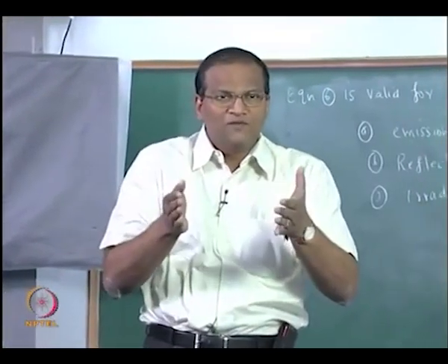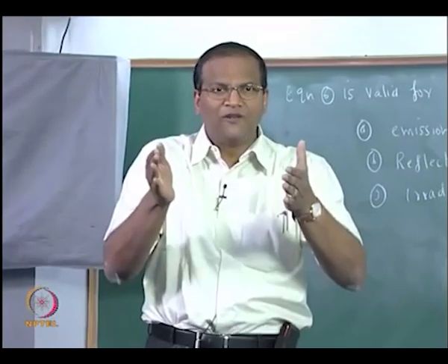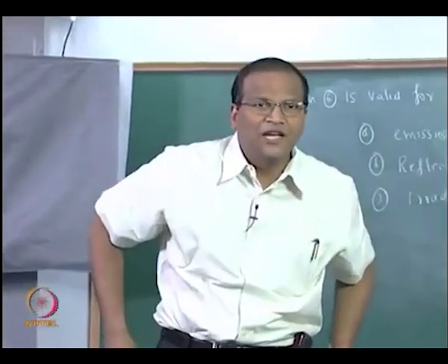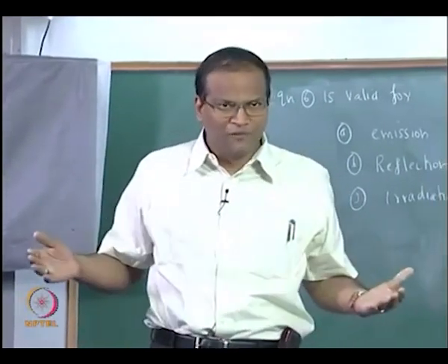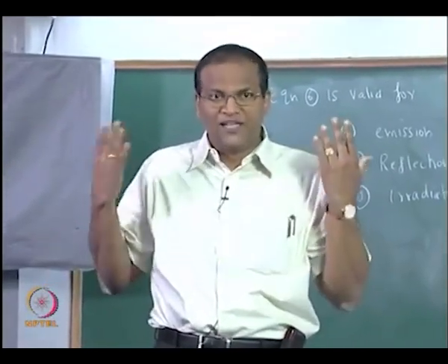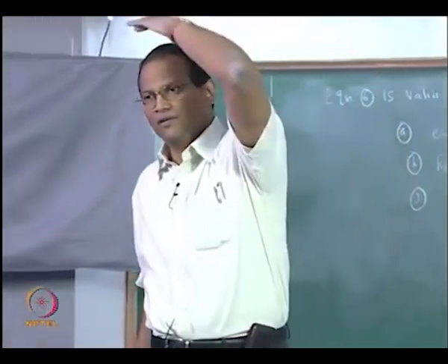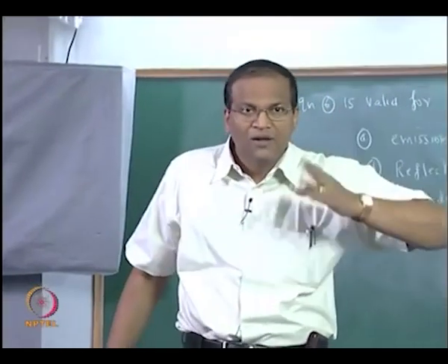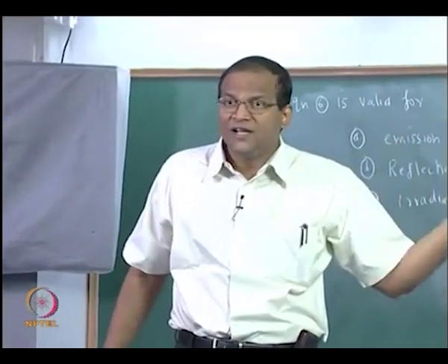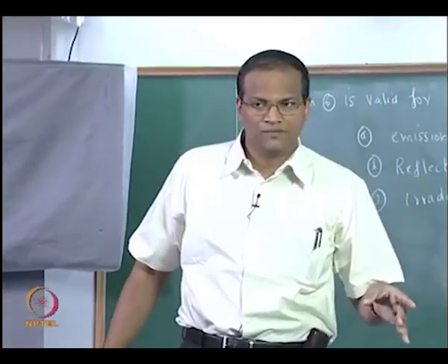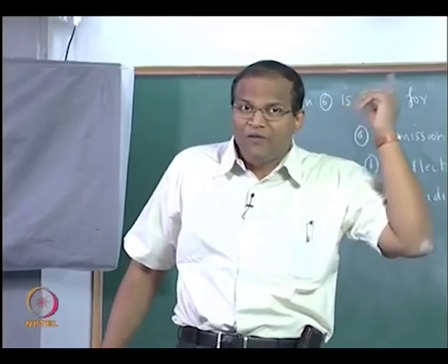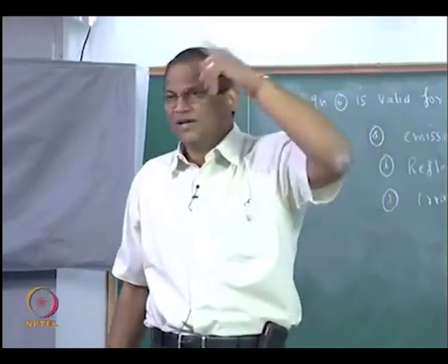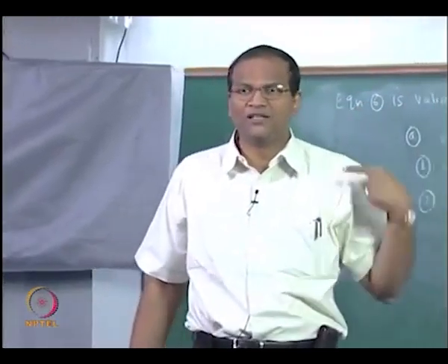Now, the beauty is that after having defined the plane, the solid angle, and after having introduced the spherical coordinate system and I lambda E, we have an excellent framework with which we can calculate the flux. The quantities of engineering interest are all on the left hand side of the equation, whether it is EB lambda or EB. Right side is I, right side is physics, left side is engineering. Whatever the physicists have figured out, we take that I and do all these integrations and get the spectral quantities or the total quantities.